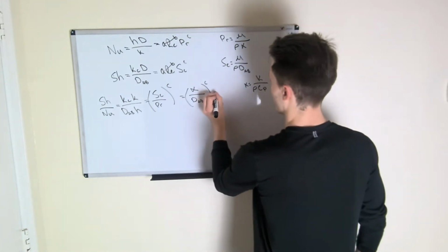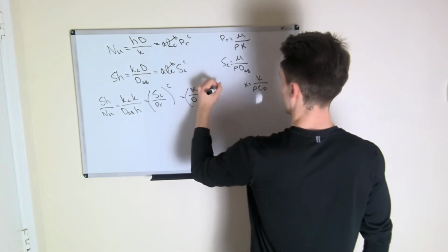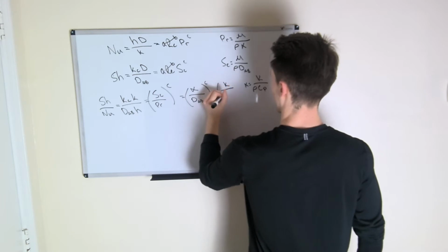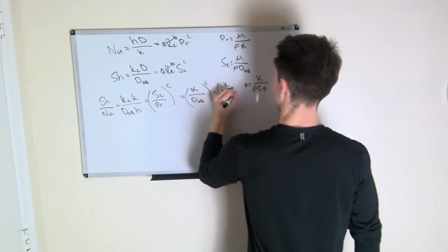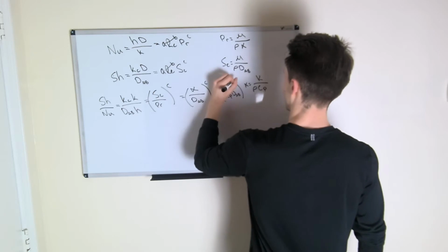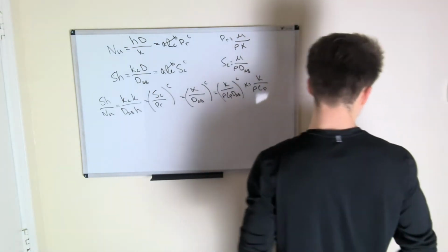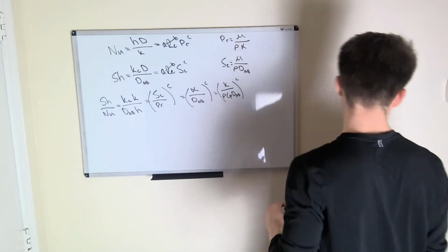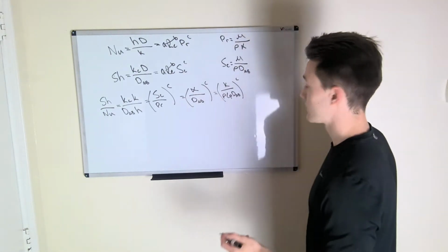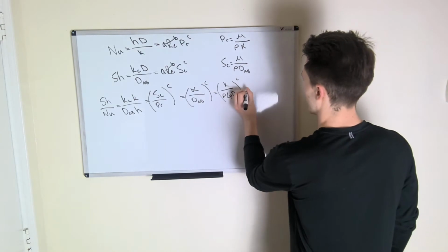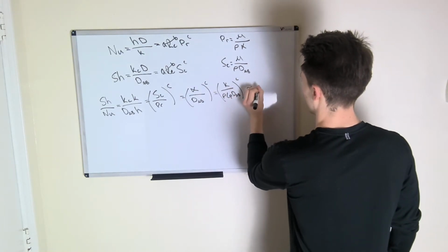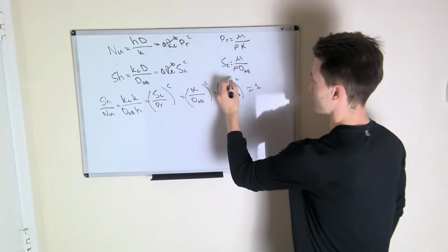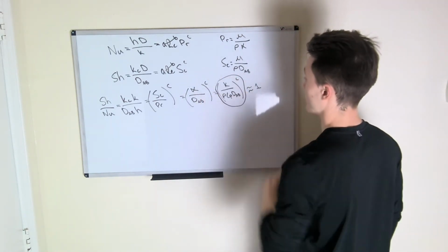And so plugging that into here, we get K over rho Cp times the diffusion coefficient raised to C. And it just so happens that by nature, for moist air, this value is equal to about 1, and this right here is our Lewis number.